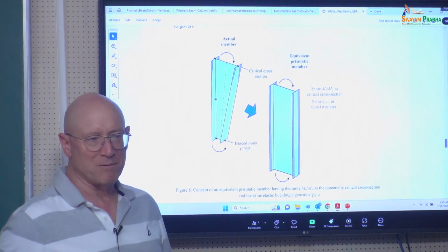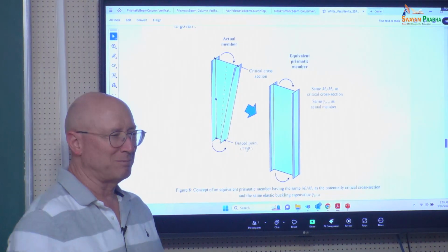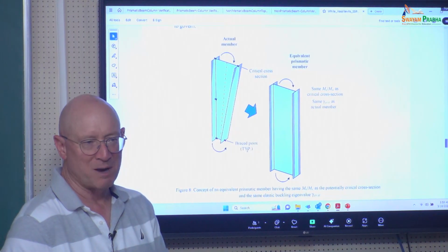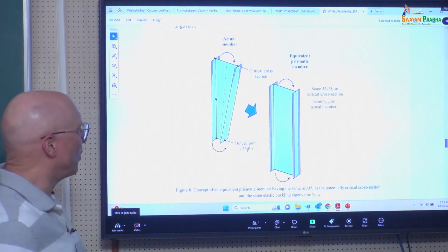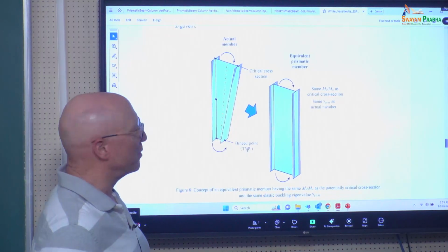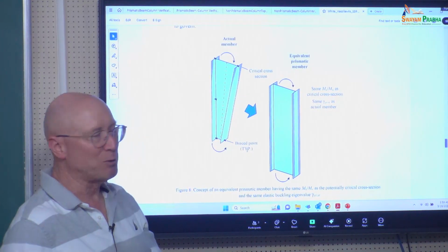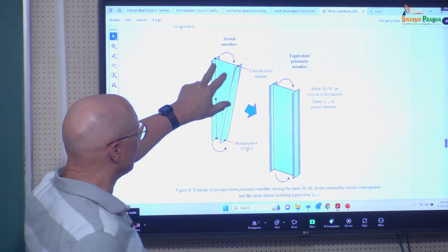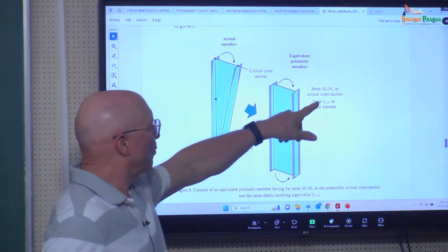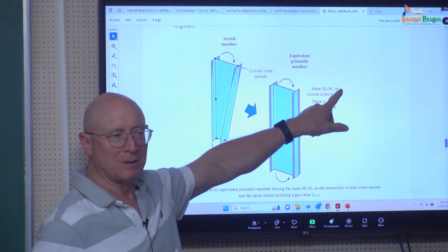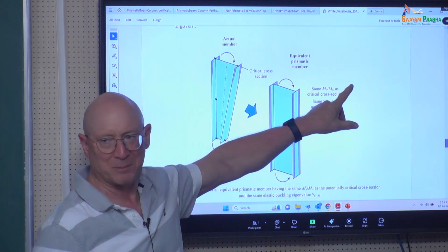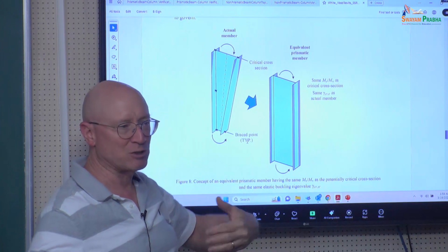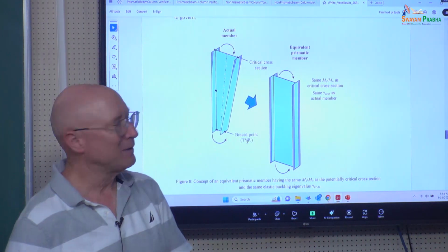In Design Guide 25, we would say, oh, well, you've got these various potential locations that may be critical. Please check them all. So once you identify a cross-section you're going to check, let's say, oh, I think the top is most critical here. You basically say, okay, well, what's the MU to MW at that cross-section? So that's like a cross-section demand to capacity ratio, okay, or cross-section utilization if you prefer that term.